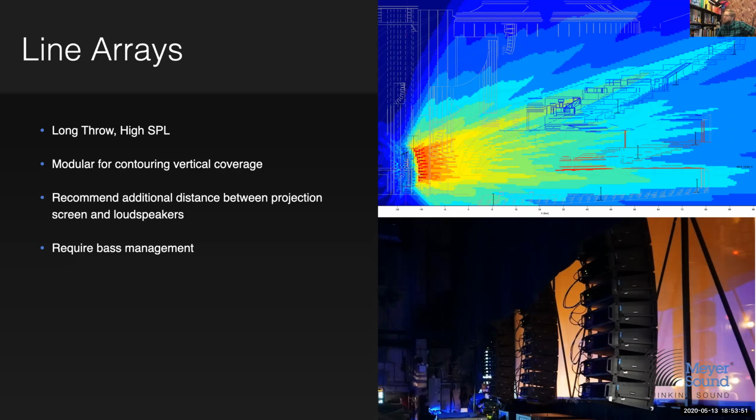And the other thing to mention on line array products, if we're doing them for cinema and to be compliant with all the standards, line array products as screen channels don't extend low like an Ashdown might. So that's when we need bass management, and we would fly subwoofers next to these line array products or on top to extend that channel's low frequency extension, because we want to have that as a discrete bass management loudspeaker system, as opposed to just putting it into the LFE.